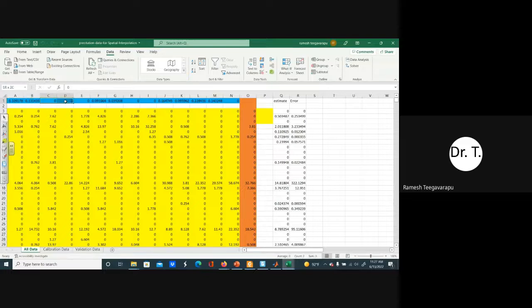And it's saying that I don't need any weights for these 3 stations, but that means these stations are obviously not useful to me. That's why it is putting 0 values there. So that means the optimization is already selecting the control points. Out of 14 stations, it is selecting 1, 2, 3, 4, 5, 6, 7, 8. Is that clear to everyone?